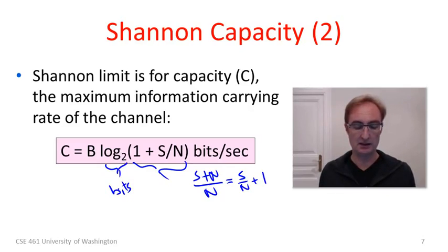The Shannon capacity is really quite fundamental for a channel. Shannon showed that it is possible to transfer information reliably over a channel up to that rate, but no higher. This was quite revolutionary at the time, when there always seemed to be errors on channels, and the only way you could get rid of them was by sending a stronger signal. Shannon really told us that in theory there exist codes so that you will be able to send information reliably across channels up to a certain rate, even for whatever signal-to-noise ratio you're sending in.